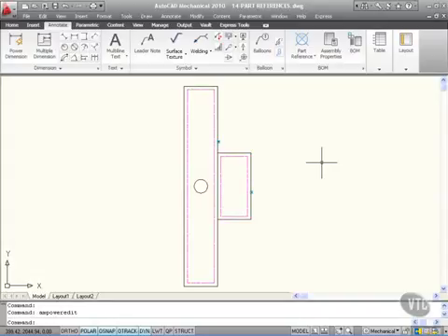So if I now wanted to add a parts list, I could, and those parts would appear on that list. So what we're going to look at now as we go through the next few sections of this particular title is how we generate a bill of materials and parts lists based on these part references.